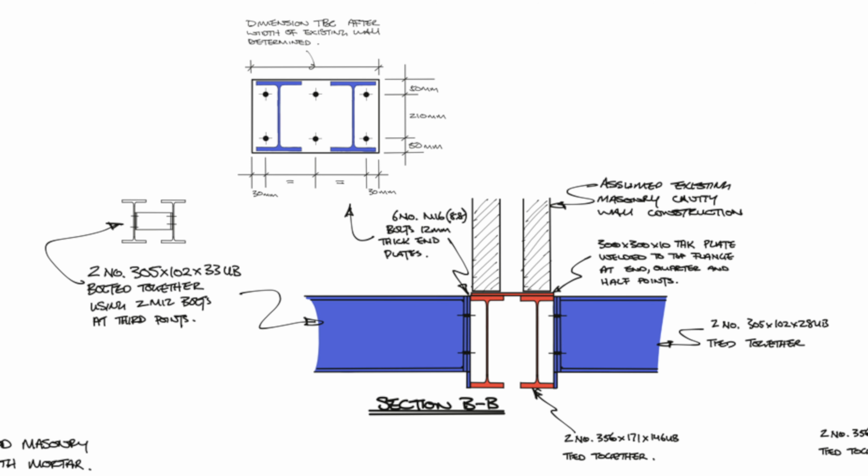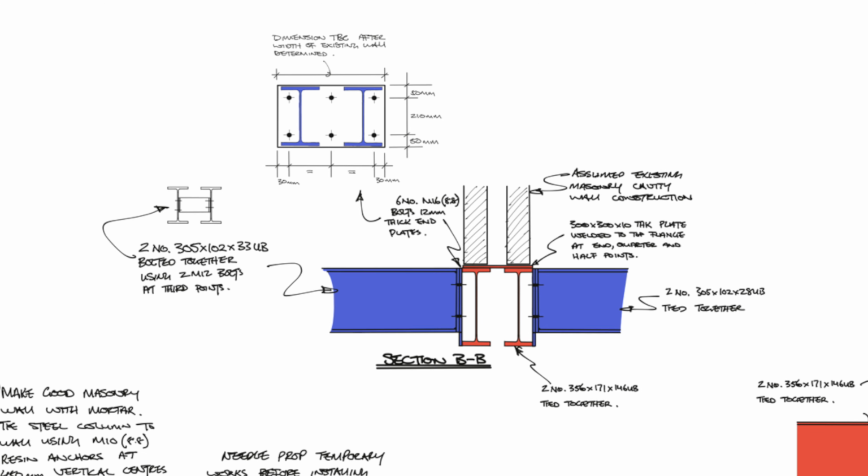And finally, a section through the main steel frame showing the intersection where I've got two incoming beams fixed to the main steel frame. Originally I didn't actually have this detail, but when I sketched it out quickly, it soon became clear that I did need to draw this detail because of how involved it would be, and your bog standard contractor may not understand it, so I thought drawing a section would make it really clear. And having drawn the main section through, I needed to draw some additional connection details just to make sure that he gets the bolts in the right place.